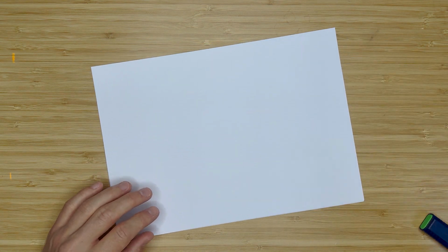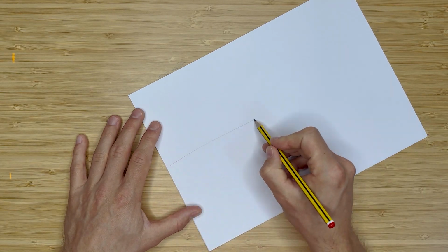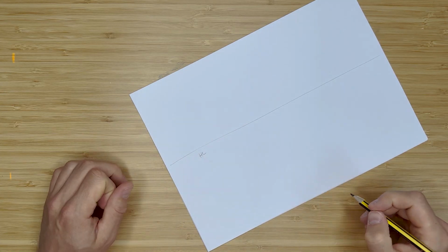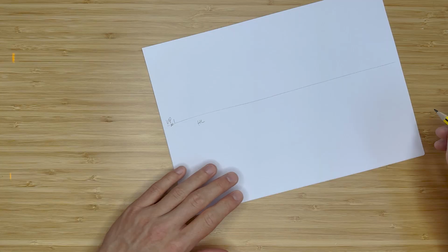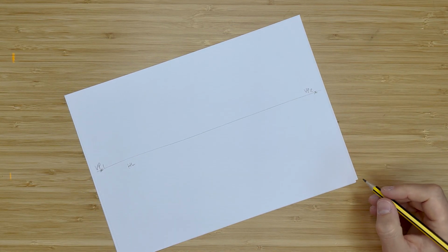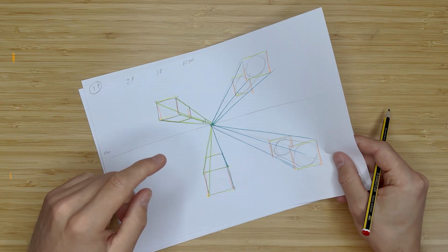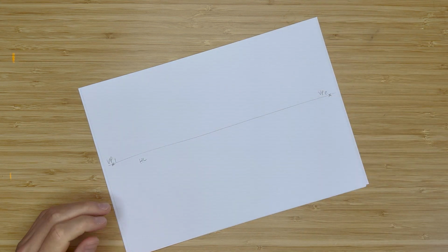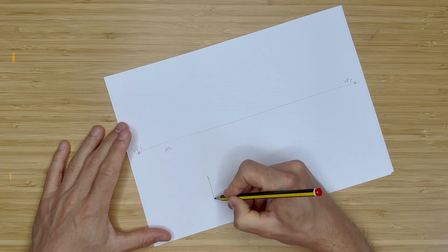So looking at 2 point perspective, exactly the same concept, except you have got 2 vanishing points. So we've still got our horizon line, call the horizon line just there, but now we would have a vanishing point 1 over here, draw an X, and vanishing point 2 over here, and we can draw an X. And you're going to have exactly the same. You can have things above the horizon line, below the horizon line, on the horizon line. So let's do 3 different cubes. It's quite common. So we're going to start with our upright.